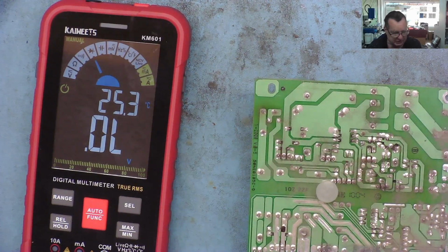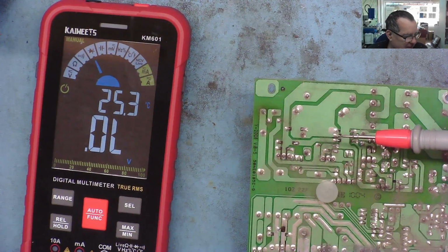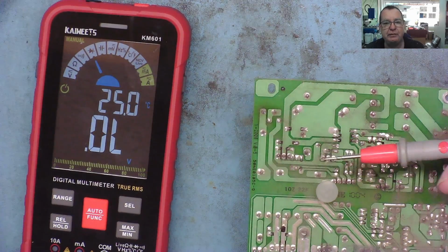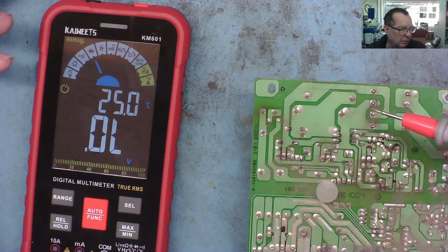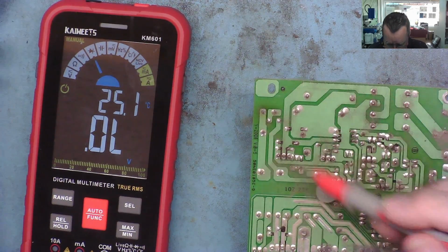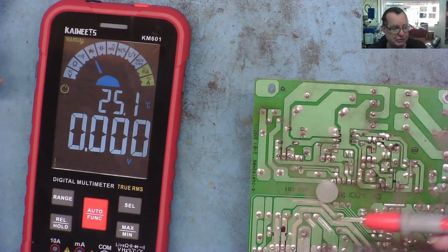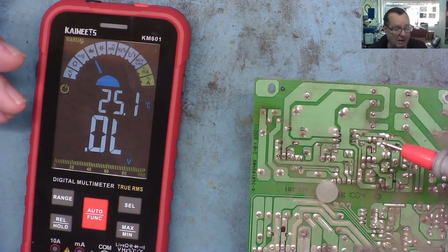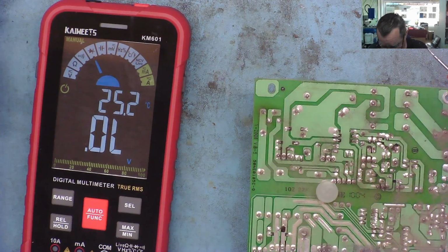When you get a situation like this, there are two ways really you can test the transistor. You can either take it out of the circuit board if you suspect it, or if you just want to test them, you can take the transistors out and just test them out of circuit. That will give you a very good indication. You'll also be able to see the gain as well. So you'll be able to, for example, in some circuits, amplifiers, you may have to match the gain. So you'll get like 4 or 8 transistors driving the output, and they have to be matched for gain. So you can also do that with a transistor tester.